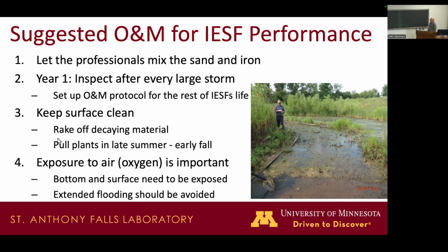Another way of handling this would be, in year one, inspect your IESF after every large storm. That can set up an O&M protocol that will last for the rest of the IESF's life. So if you have a 1-inch or a 2-inch storm, go out and check it out. Just drive by, stop, take a look. What's it look like?